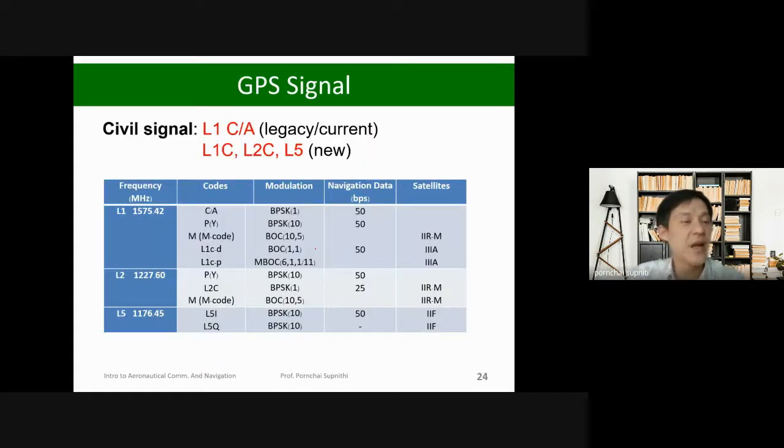So these are different names. Okay. And then for GPS signals, as mentioned earlier, we have L1, L2, and L5. We also have L2 in general for P(Y) codes, but these are for military. But for the new GPS signals, depending on which satellite you look at, we now have 3 frequencies. For each frequency, you have different signals: the C/A code, L1C, P(Y) codes, L2C, M code, which I guess is for military, and then L5I, L5Q. There are different modulations as well, and here these are the accompanying modulation schemes for each type.